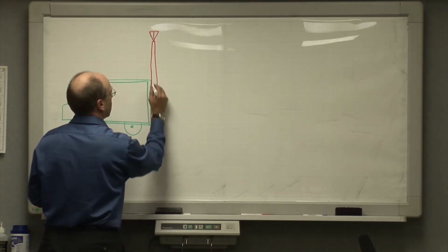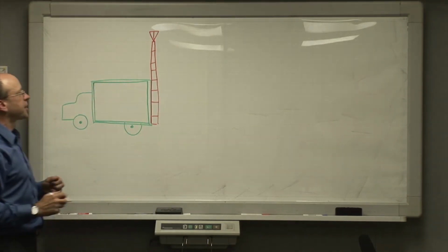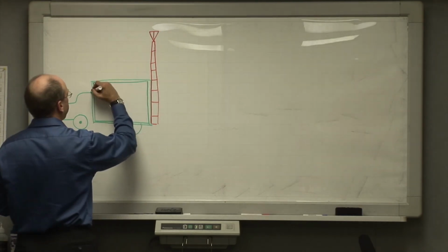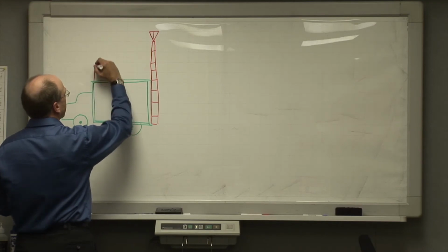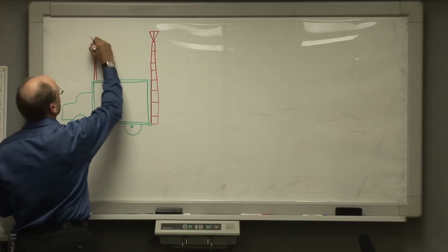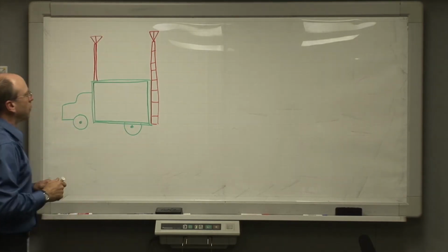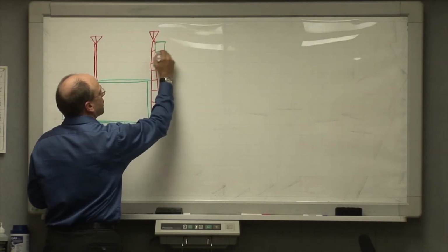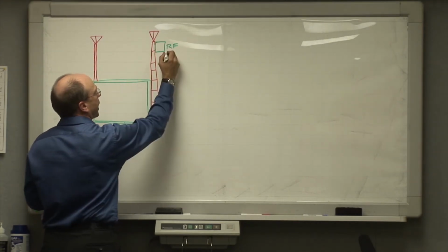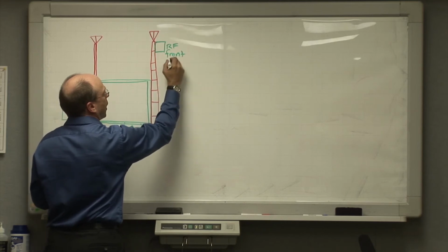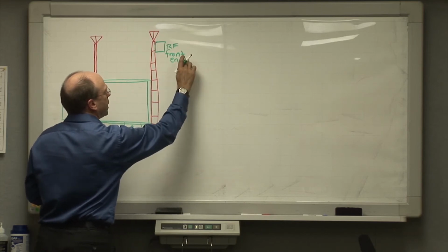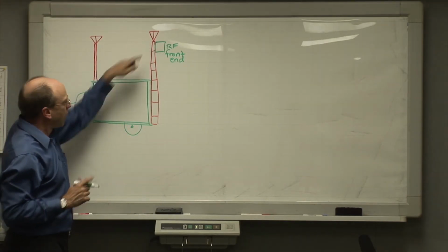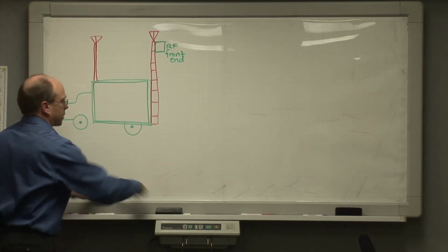And I'm exaggerating the size of the telescoping mast here, but on our current Premier measurement system, we have one of these masts mounted at the back. We have a second mast mounted on the other side of the vehicle at the front. We can put antennas on either one. Bear in mind, again, that whenever possible, we try to put the measurement system RF front end, which I'm drawing schematically, as close to the antenna as possible, so that we can use that low noise preamplification inside the front end box to overdrive the line loss that's coming